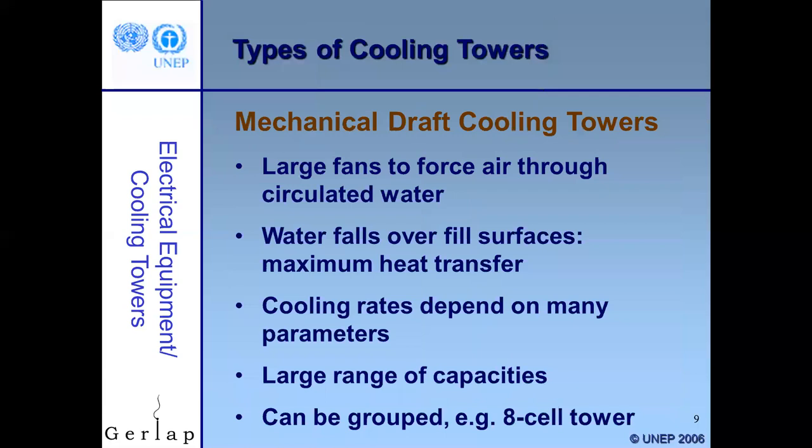Okay, moving on. So now we have what we call mechanical draft, which means we have a fan to move the air through the tower. So if it's a big tower, we can have large fans. I know the TVA Magnolia combined cycle plant has 3 generating units. They have 3 cooling towers. Each tower has 5 cells, and we'll see more of what that means, but each cell has, I believe, a 200 horsepower motor.